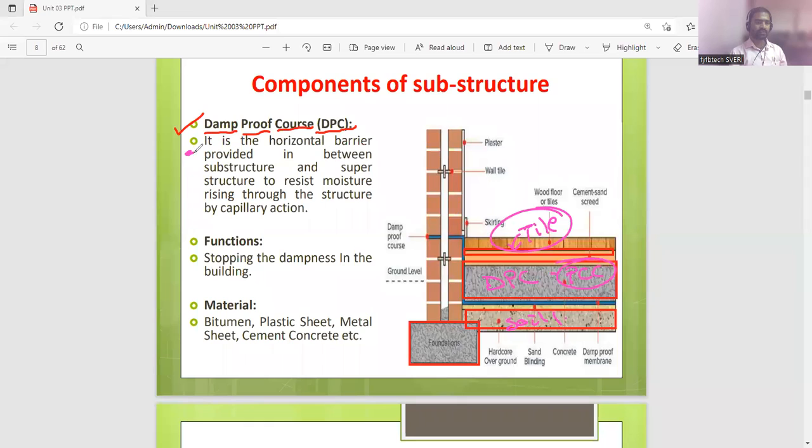Okay. See, what is the definition? It is the horizontal barrier provided in between the substructure and superstructure to resist the moisture rising through the structure by capillary action. Here there is soil. If this soil is wet, there is a chance for the moisture to rise to the tiles or to your building masonry. In brick masonry it could come inside. In order to avoid this, there is a DPC. Function: stopping dampness in the building. Dampness means water percolation, that will stop.